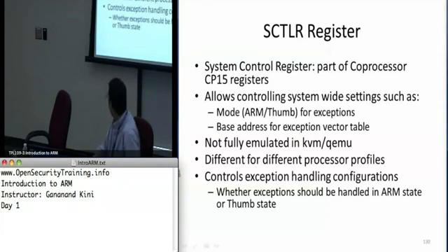If you remember, all these exceptions can occur at any point during the processor's instruction cycle, right? What this does is the vector table actually has the address to jump to start executing in that new mode. So when it first jumps to that new mode, it looks up the PC that it needs to jump to from this exception vector table, and then jumps to that piece of code and starts executing there.